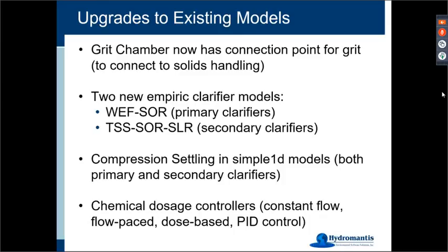For our simple 1D models, the full-on flux clarifier models, we've added a new term for compression settling, so very high concentrations at the bottom of the clarifier. You'll get a little bit better prediction of the underflow solids concentration.